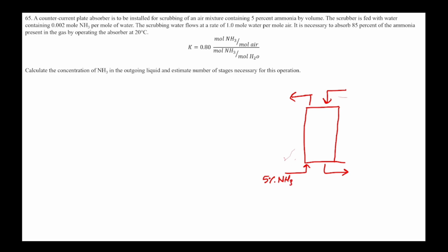The scrubber is fed with water containing, okay, so water is not pure, so X2 is equal to 0.002 mole NH3 per mole water, that is mole ratio.